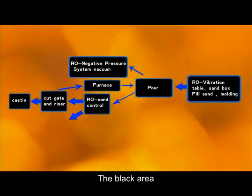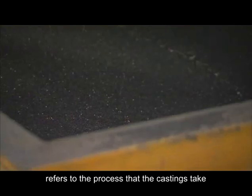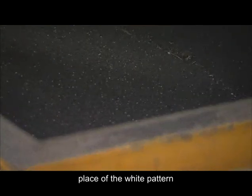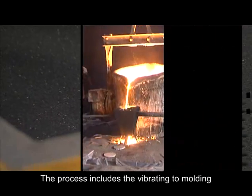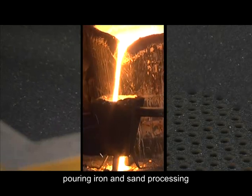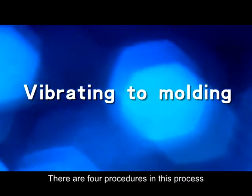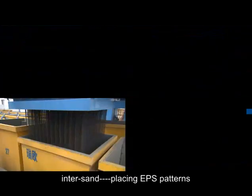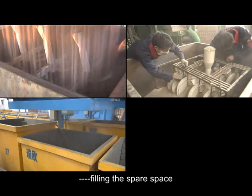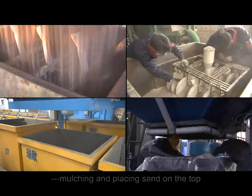The black area of the lost foam casting process refers to the process in which the castings take the place of the white pattern. The process includes vibrating to molding, pouring iron, and sand processing. Vibrating to molding has 4 procedures: bottom sand, placing EPS patterns, filling the spare space, and mounting and placing sand on the top.